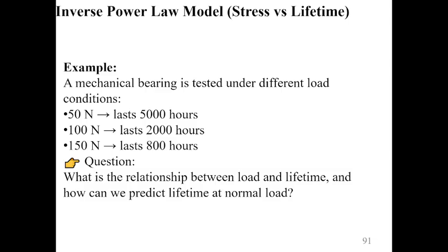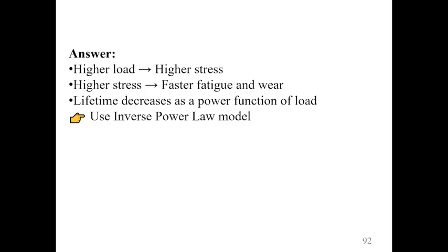Okay, in this example, we want to analyze the effect of mechanical load on the lifetime of a bearing. As the applied load increases, the internal stress within the material also increases, accelerating fatigue and wear mechanisms. The observed data clearly shows that lifetime decreases rapidly with increasing load.